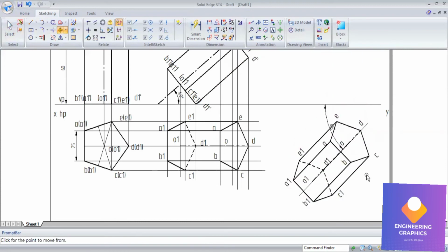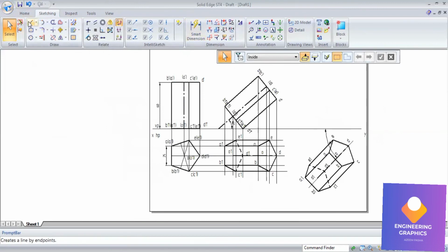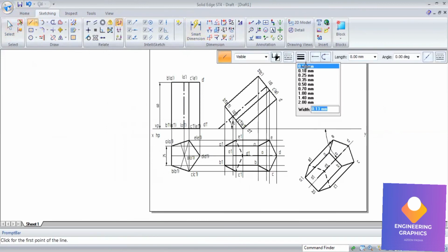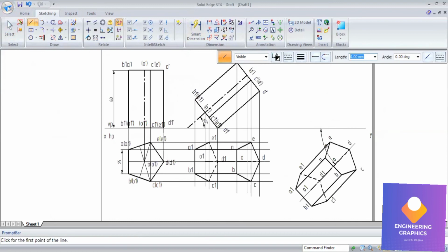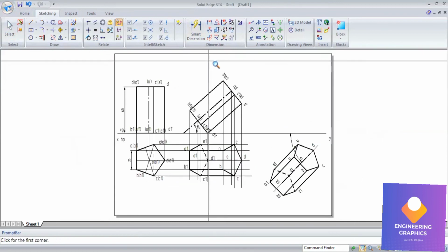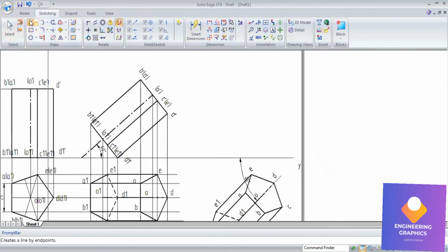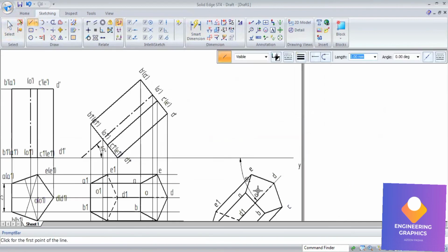Okay, so the angles remain the same here, 45 degrees. Now by projecting the lines upward, I can construct the final position here. So you can see here I am going to show the easiest method. So take zoom by area, select only the top face from the front view and the top face from the top view. Okay, you can see from A and A it is ending up here. Just move it further and end it. So this is where you get A dash.